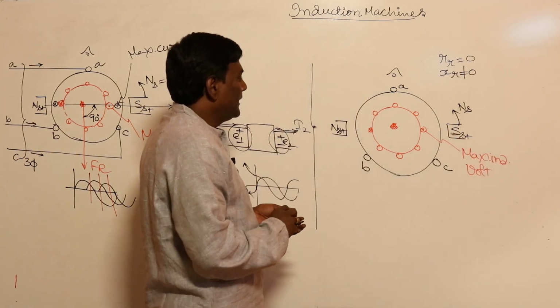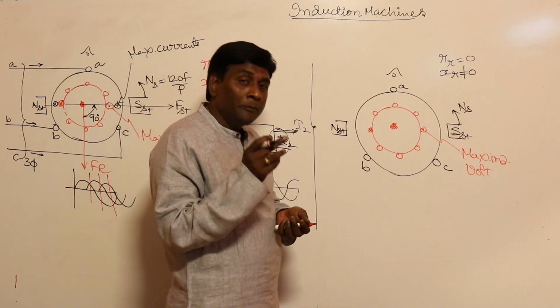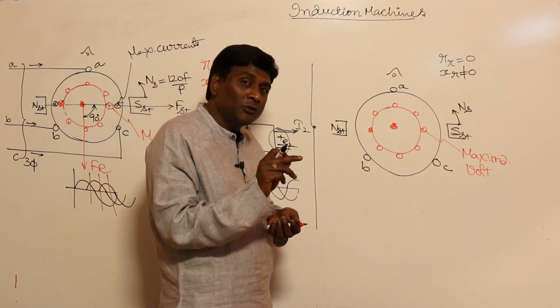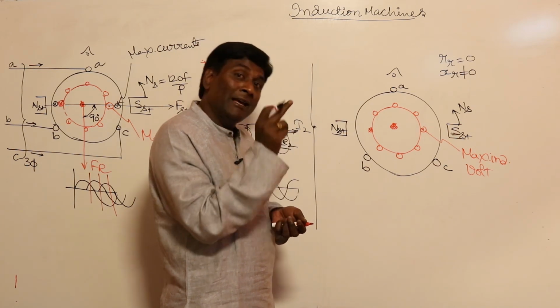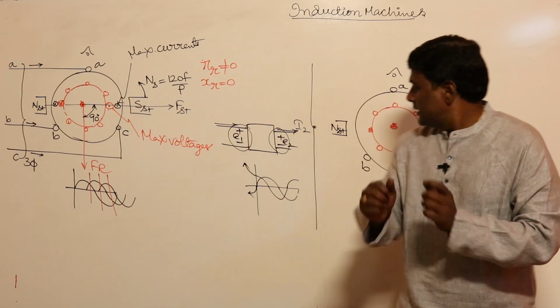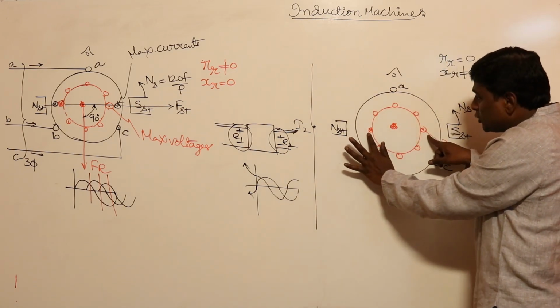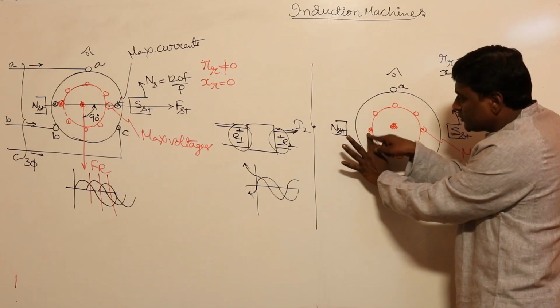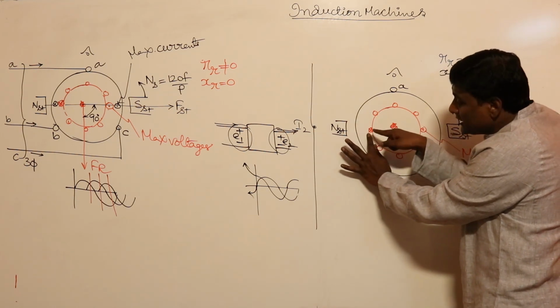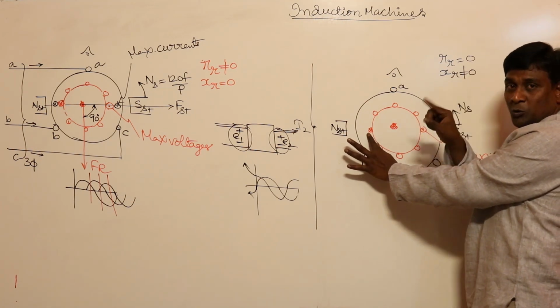Okay, now let us think of where maximum currents happen. Why are maximum currents important? Because depending upon the maximum currents only, my net resultant MMF will be aligned with the phase axis of that. Now see there, all of you, as of now induced voltage is maximum. In order to get maximum current, you have to wait for 90 degrees, because current lags behind voltage by 90 degrees.